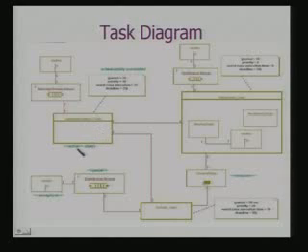I have indicated by this stereotyping that this is an active object. Since it's an active object, the thread corresponding to it should satisfy the schedulability constraints. So you have specified the period, the worst case execution time, and the deadline. These details have to be represented so that your specification becomes complete.